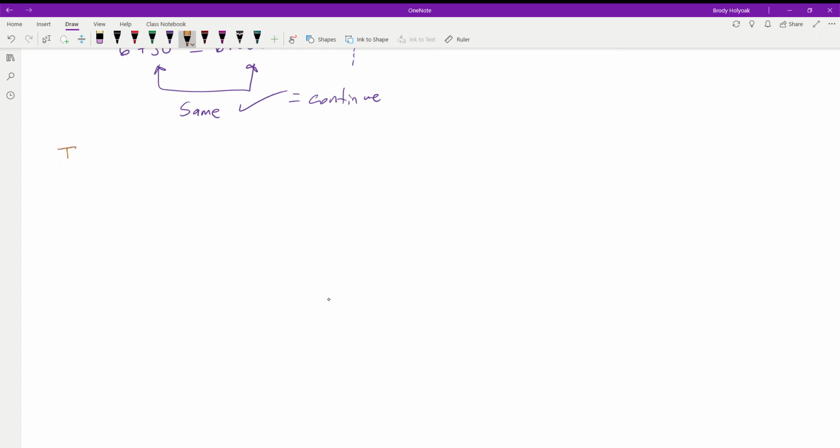So our IB is going to be equal to the voltage of B, which is the voltage of our parallel network, divided by the impedance of branch B. So we have 3.979 volts at an angle of 13.338 degrees, divided by our impedance, which is 34,630 at an angle of 86.308 degrees.